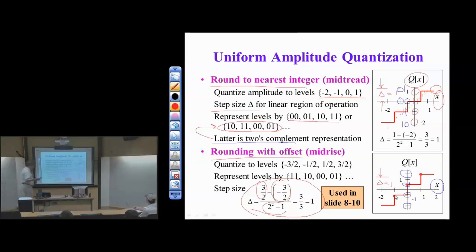Okay. Again, there's a fast way to do the comparison. If we do this simply looking at the amplitude, the voltage x that comes in, divide and conquer, right? Compare x against 0, then compare x against 1 to narrow down which level you want. And you minimize the number of comparators in that particular design. But the trade-off is I now have longer delay to get to an answer. So it's one way to do the conversion, I suppose, in analog circuitry.